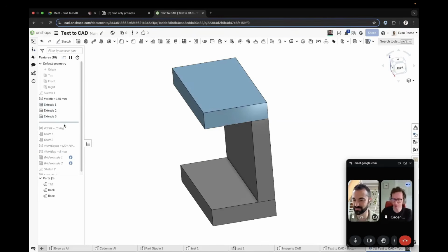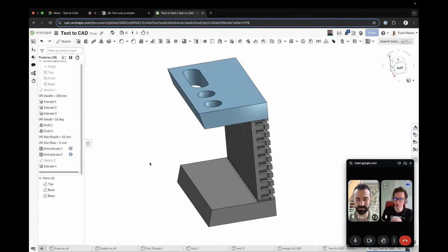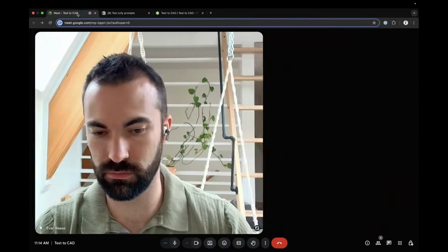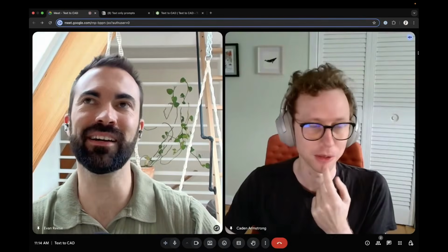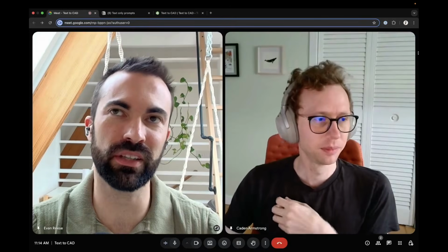But you asked an interesting question halfway through: what's the joint between these two? That's something where I've come up with a design, but I don't have a way to join them together. And that isn't in the design. So while we have a nice design, it's not manufacturable, right? It still needs that level of knowing, okay, how do I join this together? Realistically, gluing that joint would be difficult to do cleanly. And from a design standpoint, I also know that this bottom face should not meet the curve. Toothpaste gets caught in there and you can't clean it.